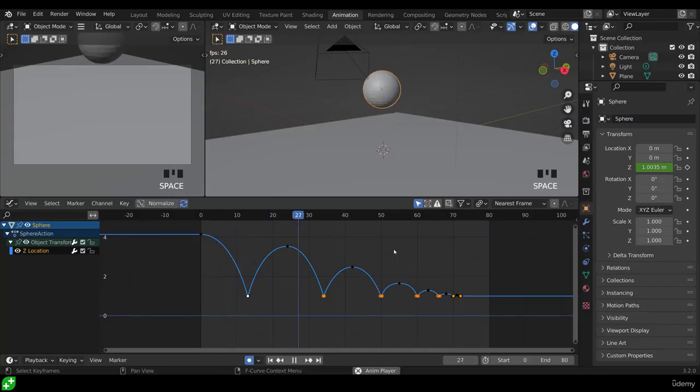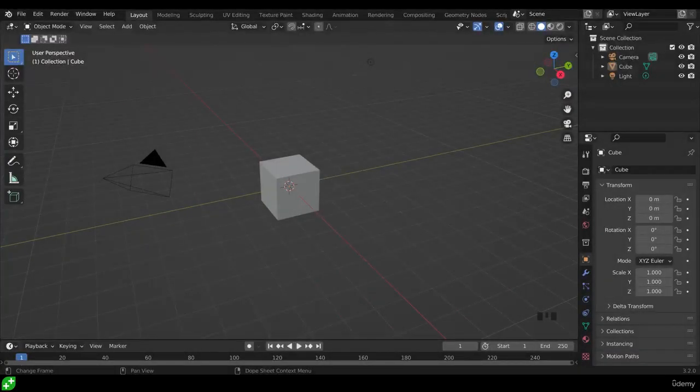In this lecture, we'll be looking at the graph editor to create a bouncing ball animation. So I've started a new Blender file, and a quick challenge to you is to add in a UV sphere and a plane for a floor. And I want you to animate the sphere so it falls from a small height over about 1 second and hits the floor and stays still. So you'll need 2 keyframes, one at the top and one at the bottom, and your animation should last for 1 second. So pause the video and have a go at that.